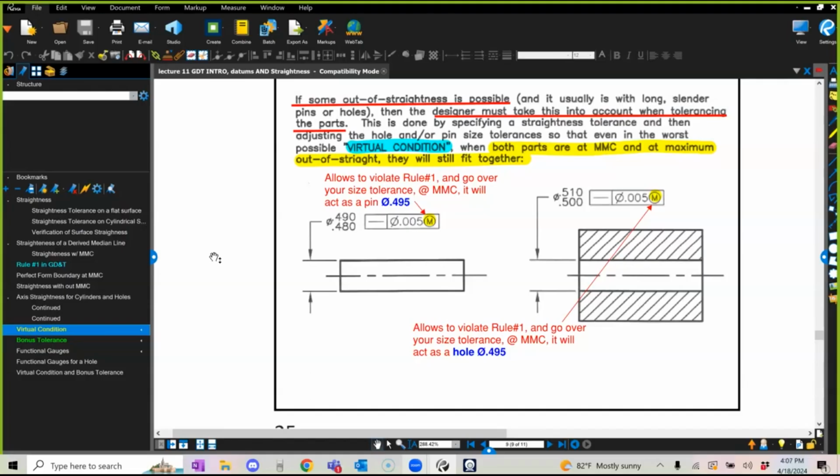I want to make it small. The worst case condition is the smallest for fitting condition, right? So I want to call it the smallest I can get. And remember, as I was getting crooked, the hole actually acted even smaller. So let's make it the smallest I can get minus the geometric imperfection. That will make the hole even smaller. Now, how do I guarantee assembly? Go and make the pin the worst case condition and the hole the worst case condition. And even after the worst case condition, if this guy still matches and it fits all together, I will guarantee assembly. Do you guys understand? Okay.